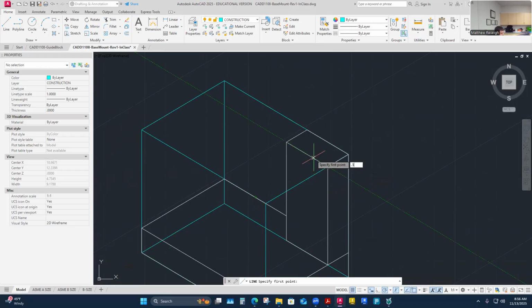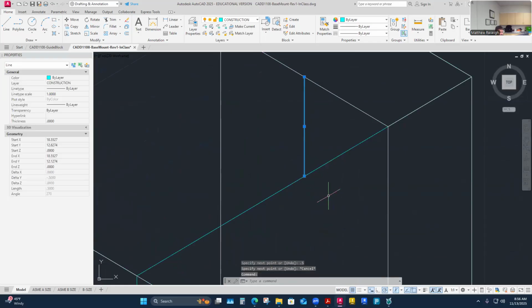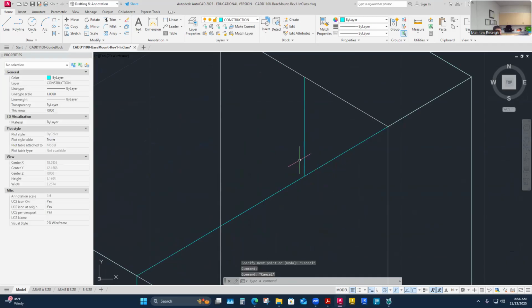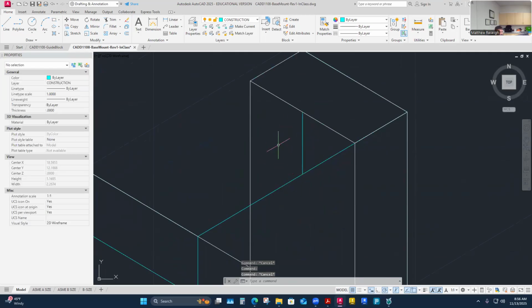So yep, 0.5. I just cursor it over, and then I'm going to... how far down are they? Looks like it's 2 inch up from the bottom, 2.5. So it should be a 1/2 inch, like that. Almost intersects my... yeah, looks like my endpoint pretty much lines up on this. It's not always the case, just the nature of how these dimensions are working out. But that endpoint of that line is definitely the center point for the features here. So I'll show you how to do that, and then we'll do the bottom ones.